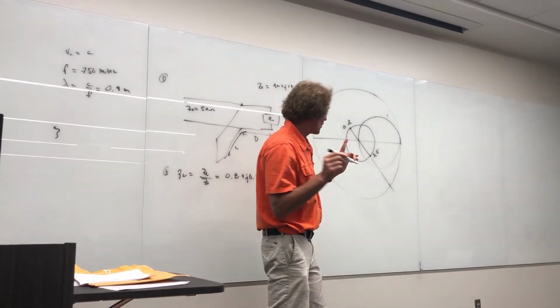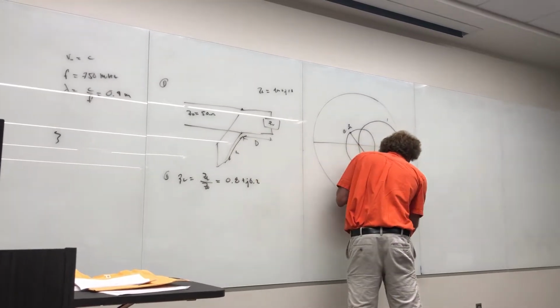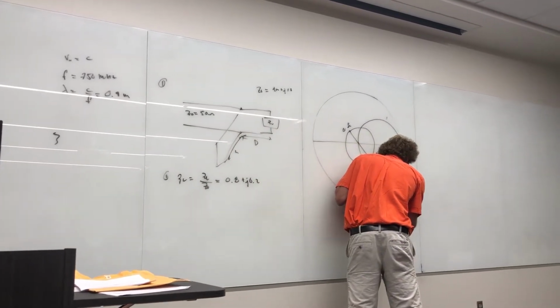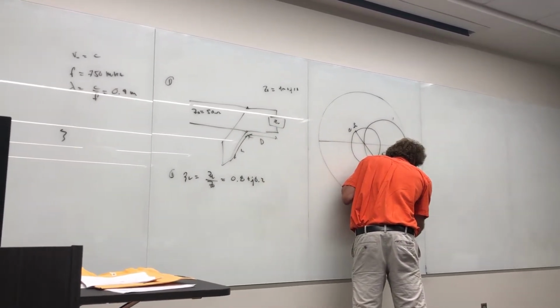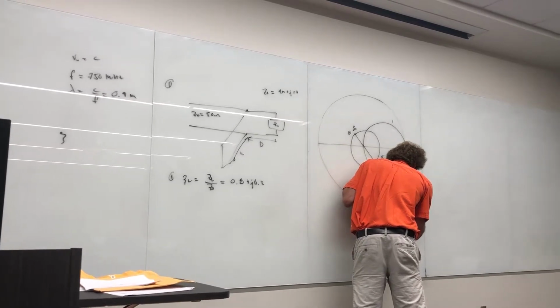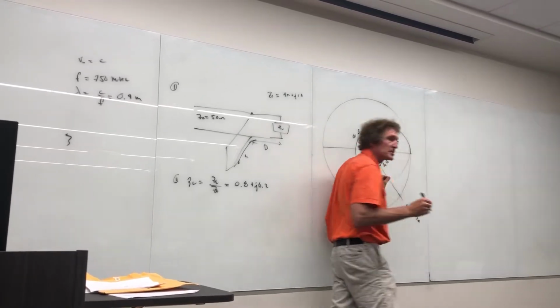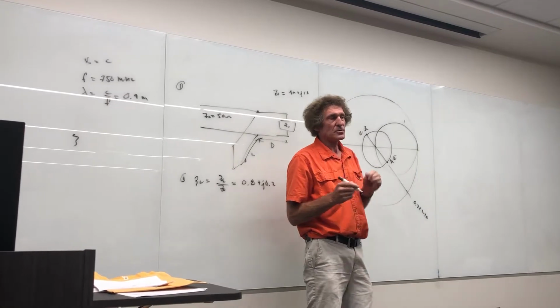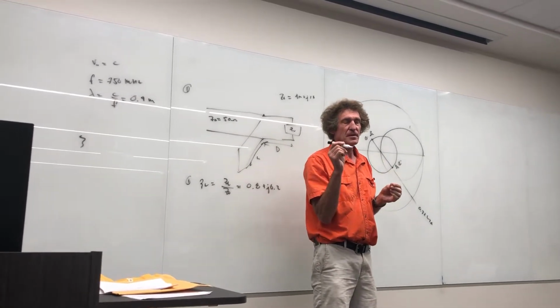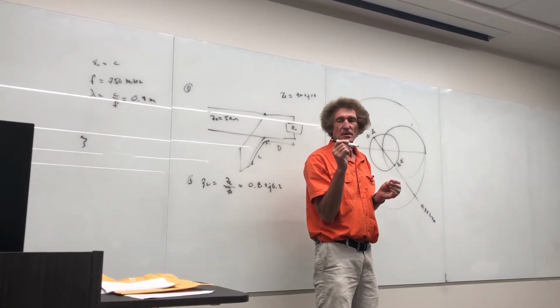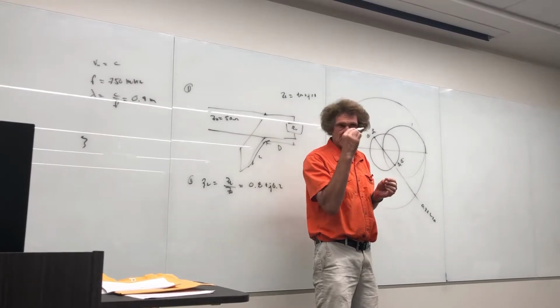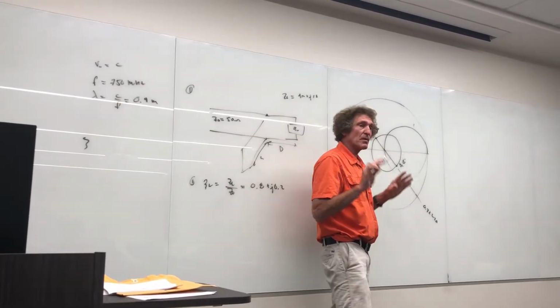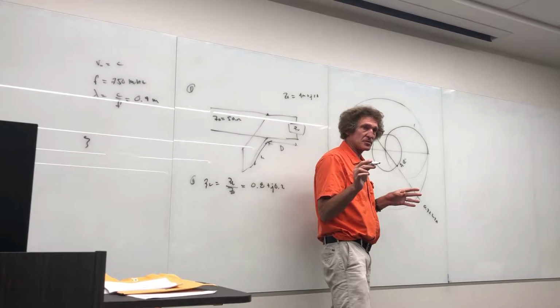All right. Now, we're at YL here. And when we look at this, I think it's 0.32 something wavelengths towards generator. Do you all see that point? What, Josh, what did you have for the exact value? Because yours was right. Yeah, 0.32. And you can just take a straight line there and see. Remember, I'm working on the outer circle, wavelengths towards generator.